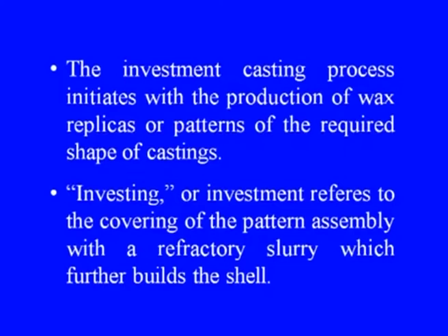The investment casting process initiates with the production of wax replicas or patterns of the required shape of castings. Investing or investment refers to the covering of the pattern assembly with a refractory slurry which further builds the shell. The required shape is invested in the refractory coating which protects it. Each and every casting requires a new pattern to be produced from the master pattern, which is made one time only.